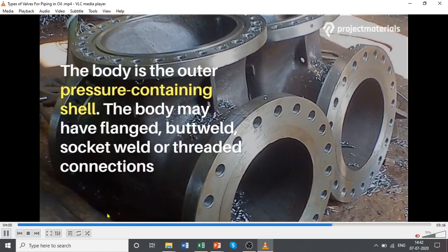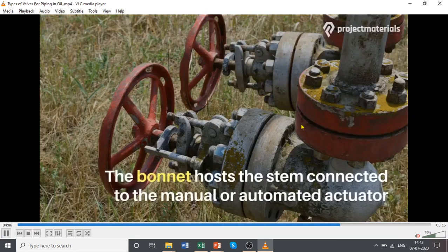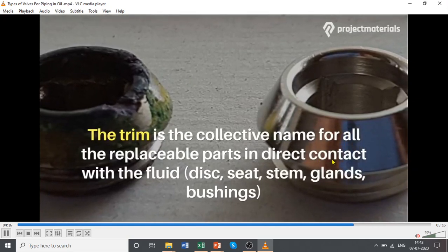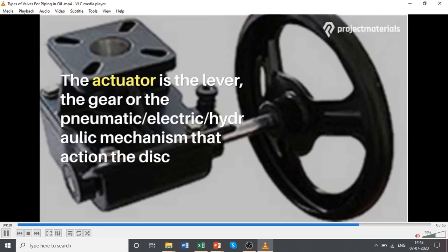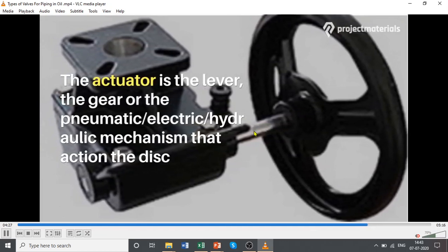So this is the body, that is the outer part. It can be flanged or screwed or welded. Bonnet, this is the bonnet. It is hosting the stem. Trim is a collective name for all the replaceable parts that are inside, so the valve seat and so on. Actuator, this is the actuator. It is what is used to control the opening of the valve.